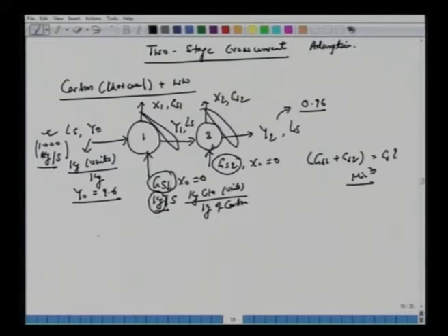Let's write down the equations which we have here. Ls times Y0 minus Y1, which is the reduction in the color amount in wastewater, will be the same as GS1 times whatever it picks up, X1 minus X0. But X0 is 0 here, so we have GS1 into X1.